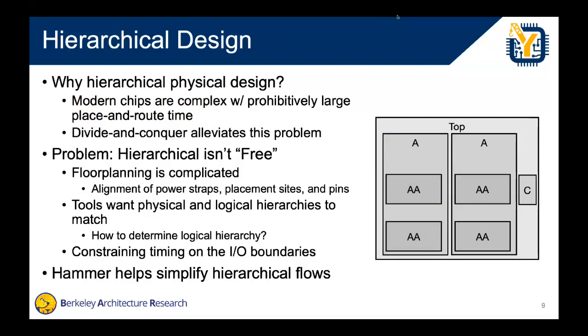So Hammer supports hierarchical design, which is a pretty common technique today where people are building large chips by hardening smaller components like a core or a cache and replicating them across the chip. Just because the number of transistors you're putting down is prohibitive for this NP-hard problem of place and route to ever finish. So you divide and conquer. This isn't a free solution. There's a lot of work that goes into hierarchical design, but essentially, Hammer helps you solve these problems in a more tractable way, and we'll talk a little more about that at the end.